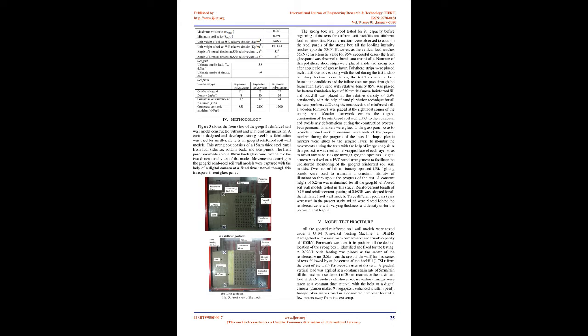A. Footing at 0.5 LR. A. Footing at 1.78 LR. Backfill fine sand, RD equals 55%, height H. SV foundation layer of soil, 85% RD. Geogrid layers, LR, wrap around facing. Geofoam 0.23 H wide. Strip load 1.78 LR. Earth pressure without geofoam, earth pressure with geofoam. B. Footing at 1.78 LR. Fig 1. Schematic cross-section of geogrid reinforced soil wall with geofoam inclusion.